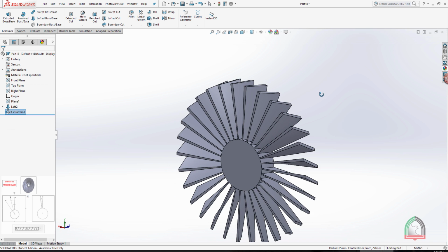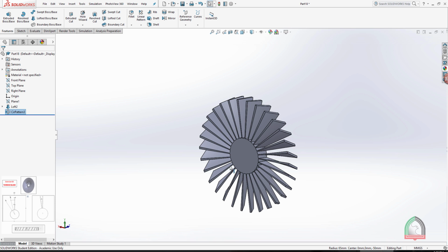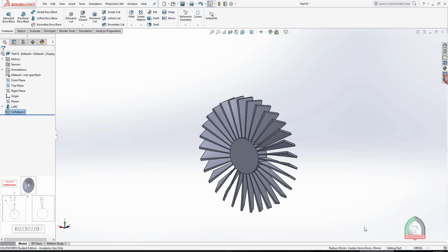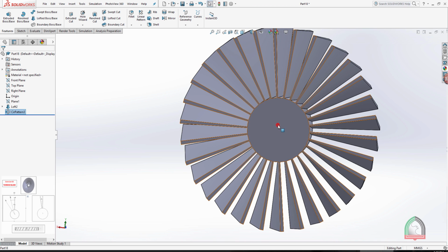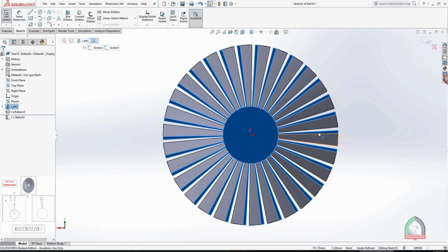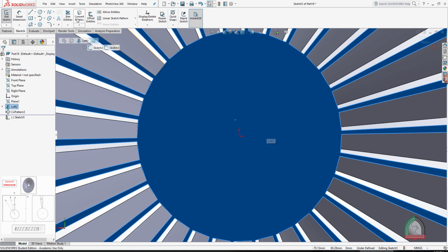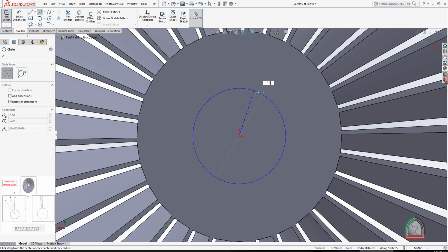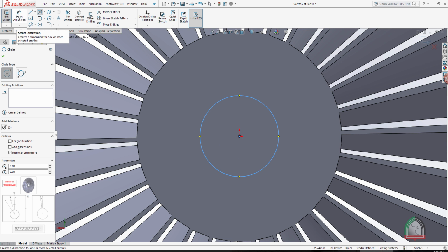So it's done. Now we can go with the center portion. The shaft diameter, I'm considering the shaft diameter as 50 and the keyhole height and thickness the same, 10. So I'm going with that one now. So I'm selecting the center face, go to sketch, spacebar and make it normal. Then go to circle, here it is, it's 50. So give the dimension here, 50.